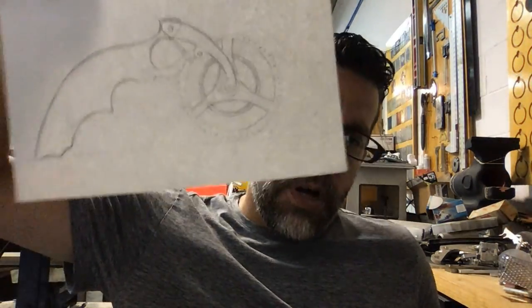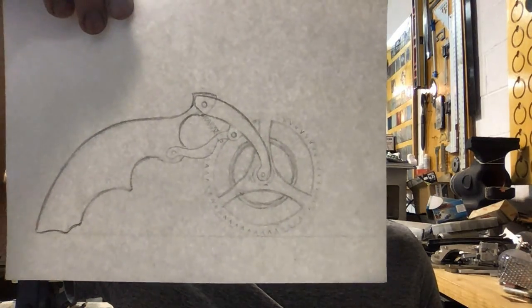Now, what I did in the case of this pizza cutter, I want the dimensions of this object to stay the same in Rhino. And this may be the case with your 4x4 design. If you made the design 4x4 inches, 4 inches by 4 inches on the paper, I want to show you how to make that translation from the sketchbook at the actual dimensions to actual dimensions in Rhino, so that when we output it to the vinyl cutter or the laser cutter, everything stays intact and there's a direct correlation between those. So what I did, I took a ruler.